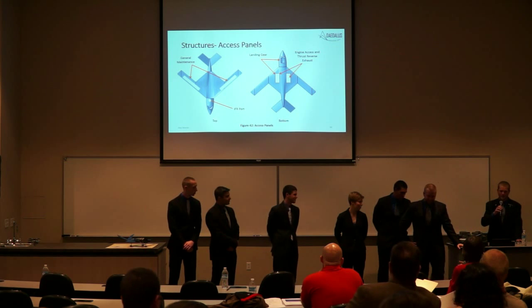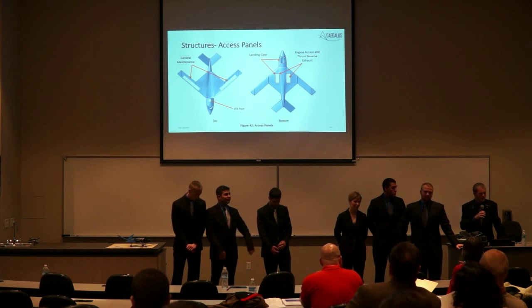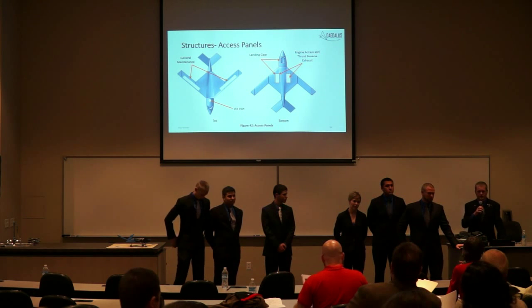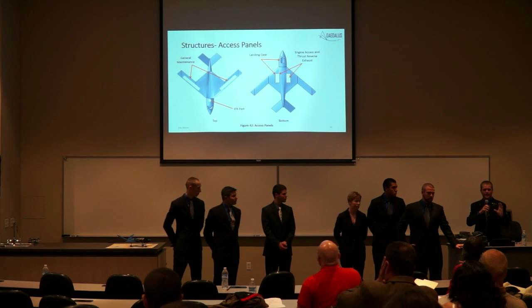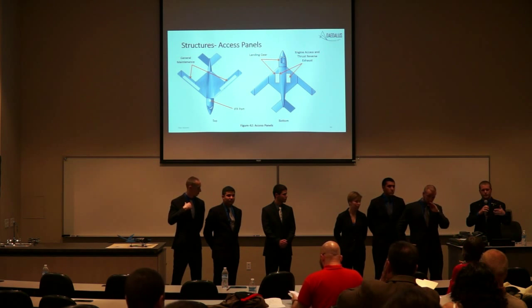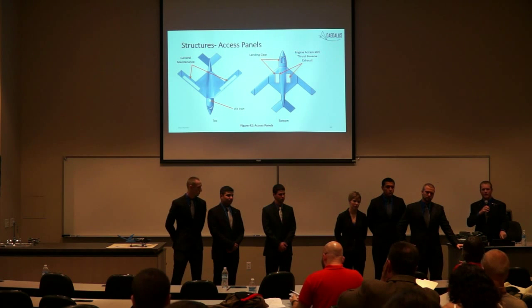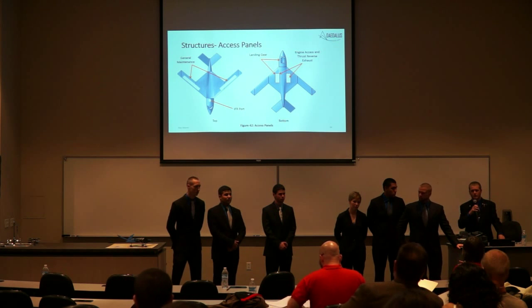That was more my department as far as the modeling, which again hasn't been done yet. It's going to be done more in detail. So the bypass reverse thrust that we looked at for a lot of the CFMs, it's not a clamshell, but the type where they move back and move in to block that free stream. We would then have a duct around that which ducts all of that air down and out the bottom, so virtually all of the bypass flow is ducted out the bottom.